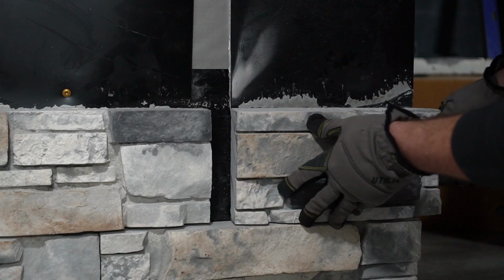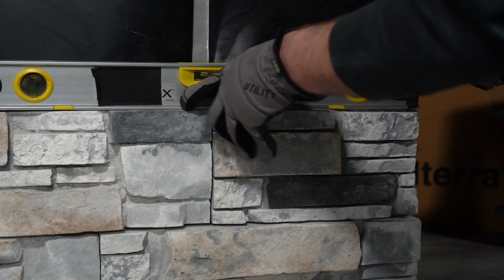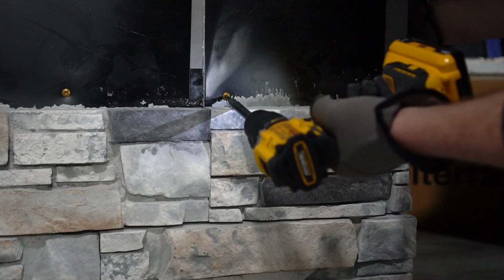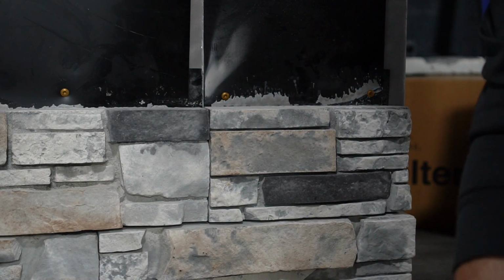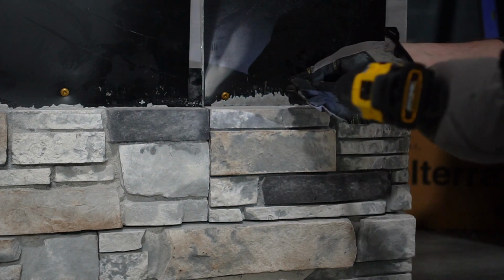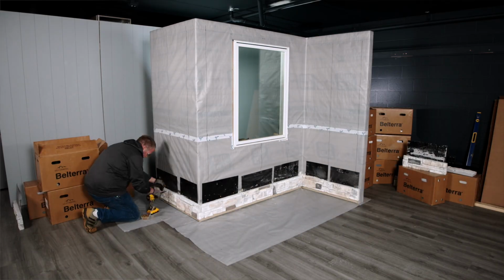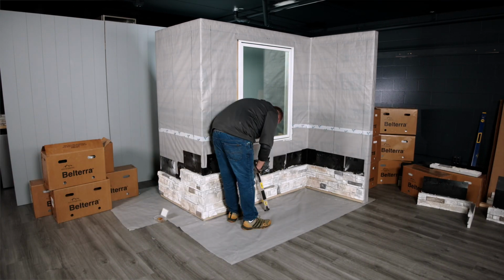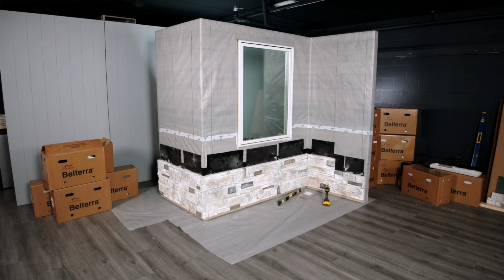The panels should be staggered by a minimum of 6 inches from one course to the courses directly above and below. To avoid alignment of vertical joints, panels must be installed level and plumb. Remember, install outside corners on the course you are working on before installing flat panels. Alternate left and right corner pairs as you work your way up the wall. This will help prevent the alignment of vertical seams and maintain the necessary 6-inch offset.